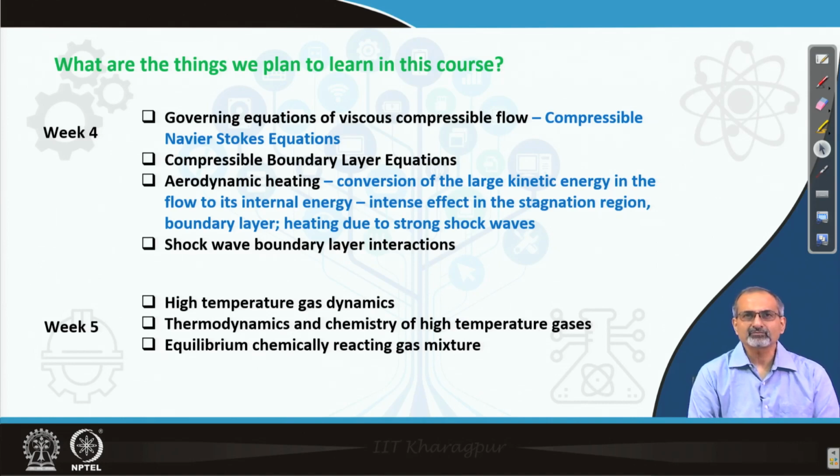equations. And when we try to analyze the boundary layer equations, we do find that as the free stream Mach number of the flow becomes higher and higher in the supersonic regime, we do find very large temperature increases in the thin boundary layer adjacent to the body. And this is one of the reasons why aerodynamic heating becomes a severe problem as the flow speeds up.